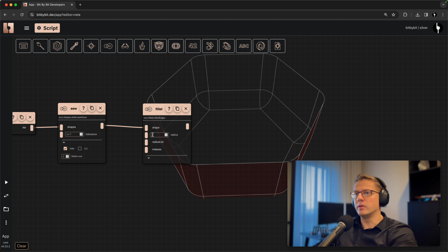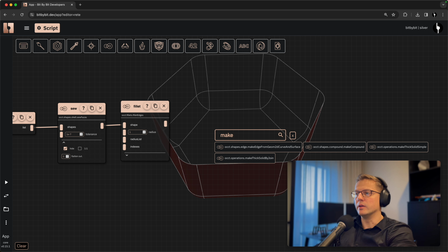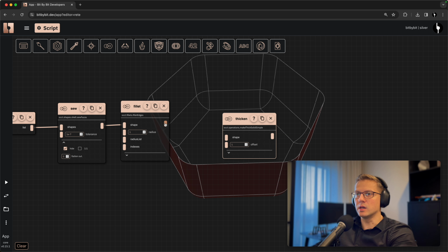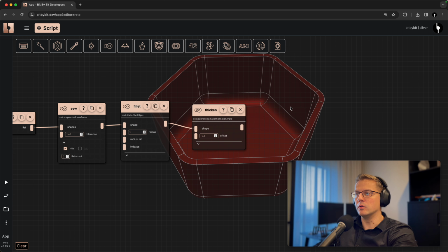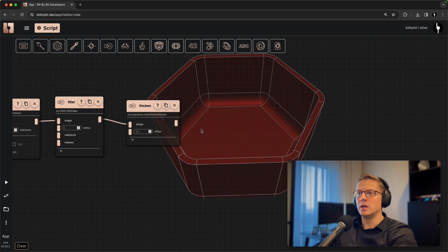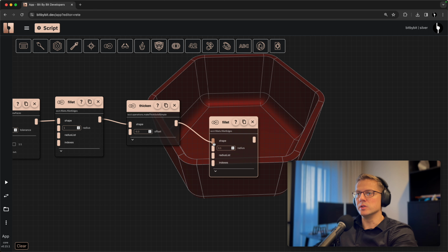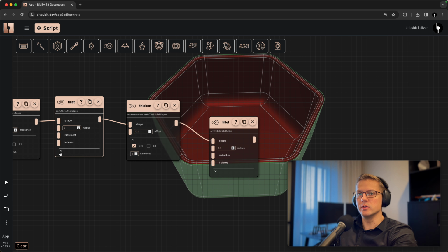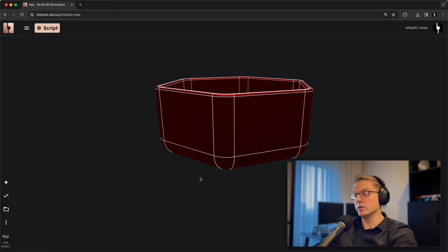And the only thing that is lacking is we want to also have a solid and not the shell. So let's thicken this shape, and I will just use -0.3 here to go inside the shape, and I will fillet that again by using 0.1 radius. You see that now we also need to hide the previous step for this to look better. Okay, so this is our end result of the model.